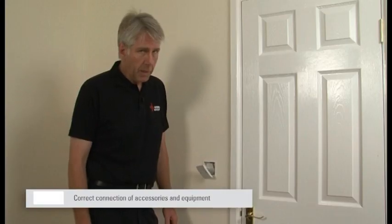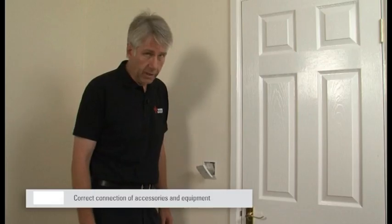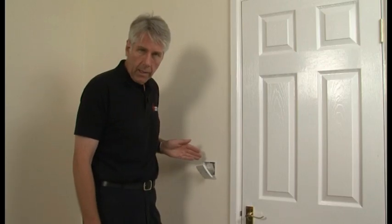The next item, correct connection of accessories and equipment, would be inspected at the same time as a number of other items we've seen. For example, connection of conductors. Again, we're checking that conductors are connected to the correct terminal and that the terminations are both mechanically and electrically sound.